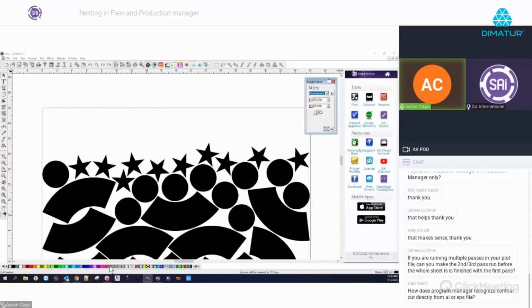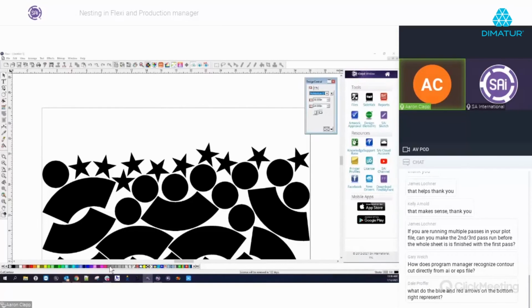So it doesn't have to be gray. It could be pink, red, blue, teal, black. It could be any color you want. So all you have to do in Illustrator, CorelDRAW, or any other application is define a spot color and then name that spot color cut contour as it's labeled here. So capital C for cut and then capital C for contour with no spaces.